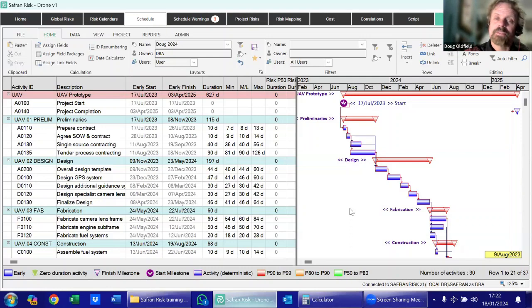And so sometimes this is something we see where in P6 you have a 3-point estimate for your minimum, most likely, and maximum. We can't do Monte Carlo in P6, and so although those values might have been created from a duration uncertainty perspective, they don't really mean all that much until we put a distribution with them and start running a simulation. And so what we've got here is a schedule.